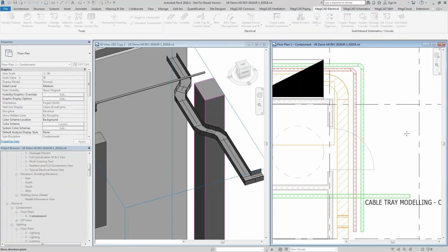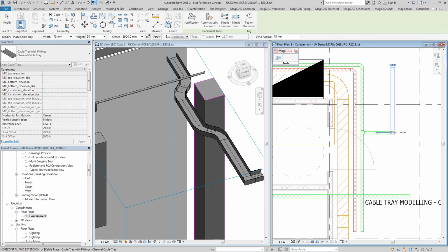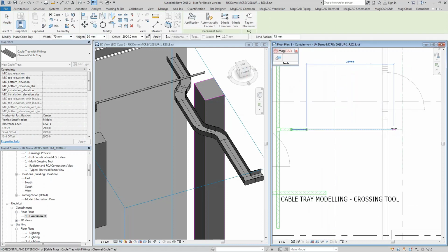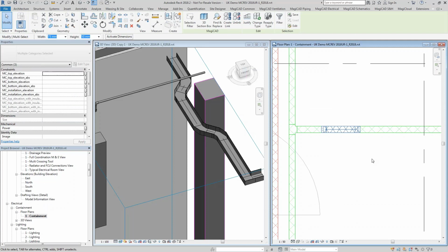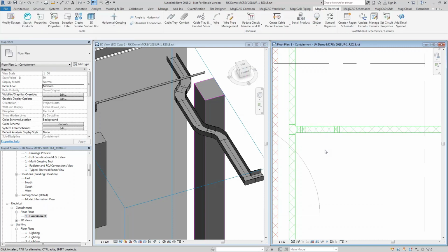And then I want to draw that off this side, then it will put the minimum amount of fittings that Revit will allow for drawing that adjustment in height as far as I've specified. Now, obviously there is a bit of tolerance here. You can move these pieces around as you normally would in Revit, but because Revit has very strict rules on how it can put these fittings together and what distances it can put in there.